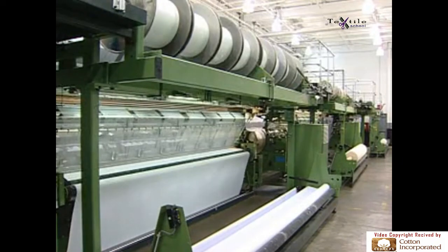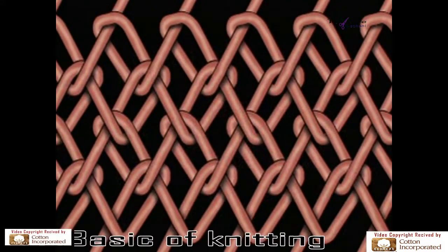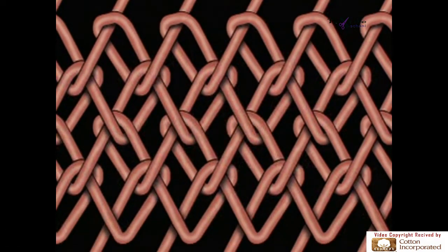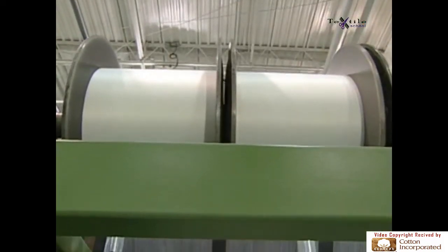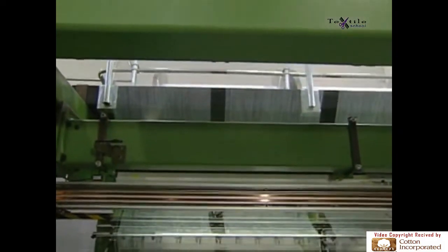The second system used for knitting is produced by machines that are designed differently, to vertically knit. This illustration shows you how warp knitting, in contrast to weft knitting, is accomplished by forming loops in a vertical direction. If you look closely at an illustration of warp knit, you see that the yarn is intermeshed vertically with 2 wales. With warp knitting machines, each individual loop is created from separate lengthwise yarns.